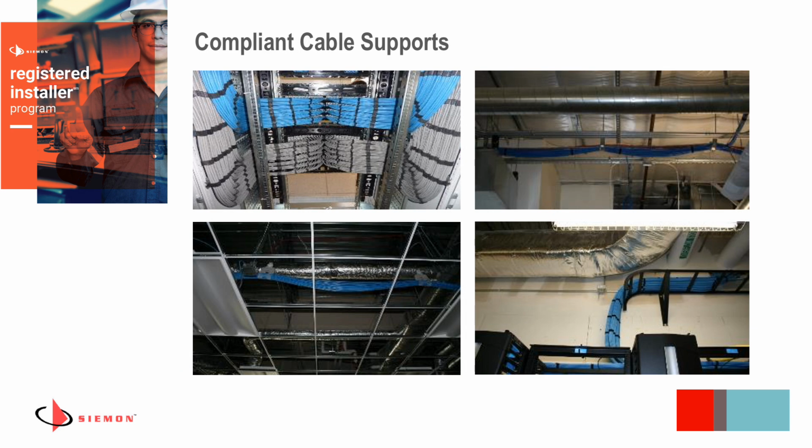On this slide, we've highlighted some nice cabling support elements, whether we've got some J-hooks or some plastic types of J-hooks, as well as ladder tray and Velcro bundles. So you can see there's nothing here violated. Everything is operated and installed independent of the other systems, not attached to the ceiling grid or anything like that. On the next slide, we'll show maybe what not to do.